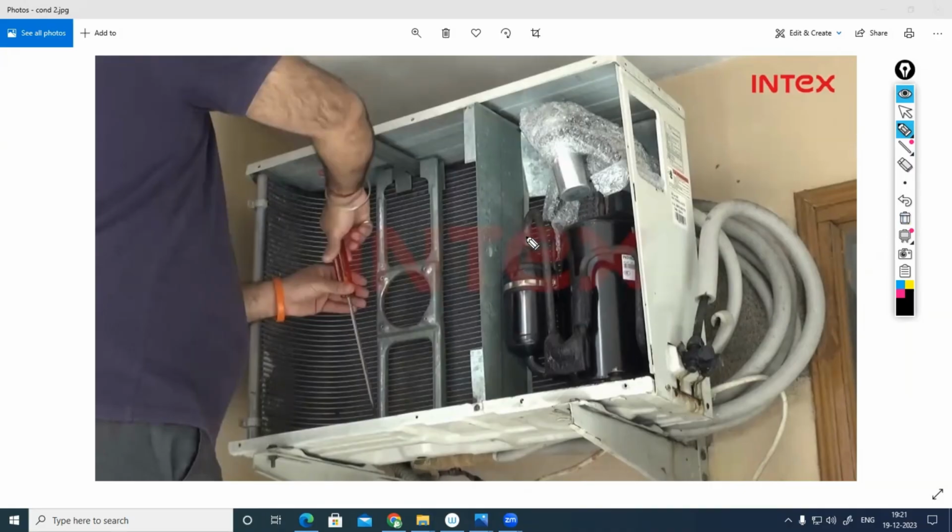We know from the compressor, the refrigerant goes to the condenser. After the condenser, the phase of the refrigerant will be liquid only. That liquid refrigerant will be going to the expansion device. Then it is expanding within the evaporator. Then the refrigerant will be evaporating by absorbing the room heat. That's why from the outdoor unit to the indoor unit, normally liquid only will be traveling.